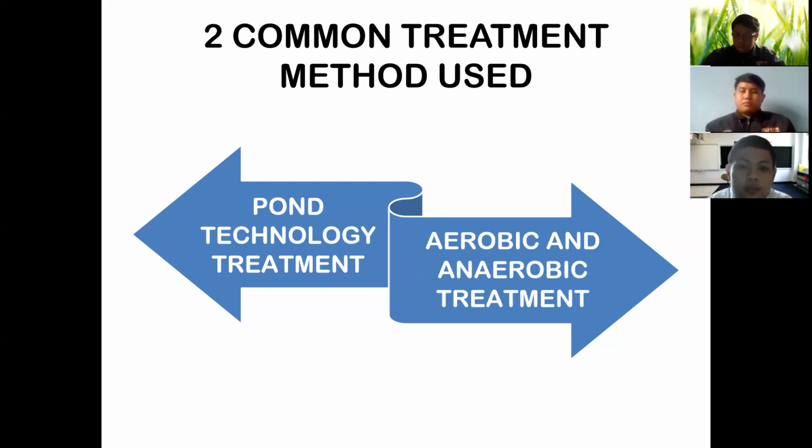Before the pond treatment system, there is a latex trap and a neutralization stage as a pre-treatment step. If the ponds are effectively designed and optimally operated, they can remove over 95% biological oxygen demand from rubber wastewater. Effluent with a BOD level of 50 to 100 milligram per liter can normally be achieved by this method. So basically this method can maximize the removal of biological oxygen demand.